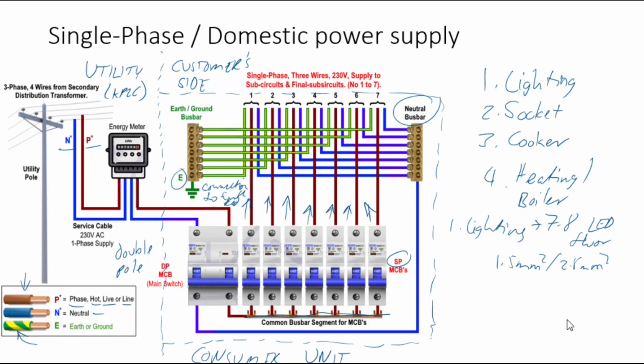And you would have parallel connection such that you have lights being connected, looped from one point to the other, which is the most convenient way of doing so. So when you have lighting circuits, the main key aspect of lighting circuits is switching, which we will now look at.